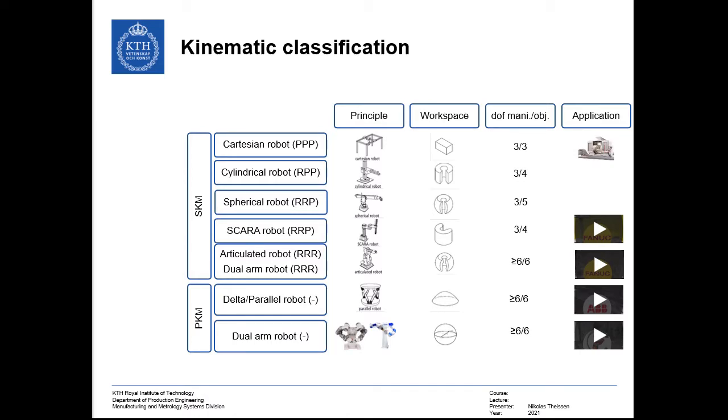The two most commonly used types of joints are the ones that allow for translational or rotational movement. The prismatic joint is the most general one-translational-degree-of-freedom joint, colloquially also referred to as a sliding joint, and it enables translational linear motion between two links. Then there is the revolute joint, which is the most general one-degree rotational freedom joint, colloquially referred to as a hinge or pin joint, and it enables rotational relative motion between two links.